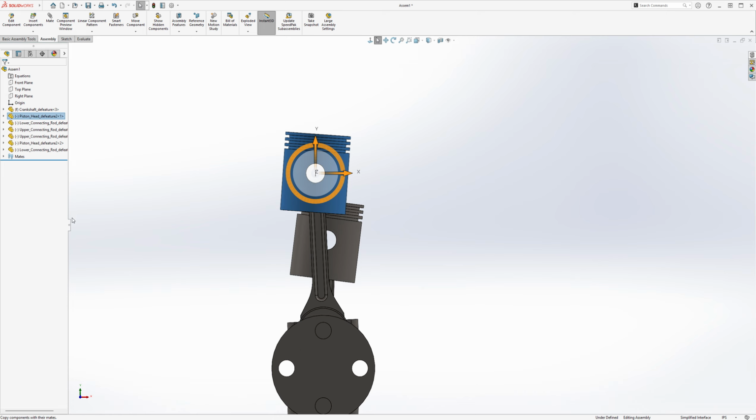How do I show its planes? Oh, reference geometry? Oh, here it is, okay. So if you right click the part in the feature design tree and you go to reference geometry display, and then you hover over it, it'll show you the option for show primary planes.